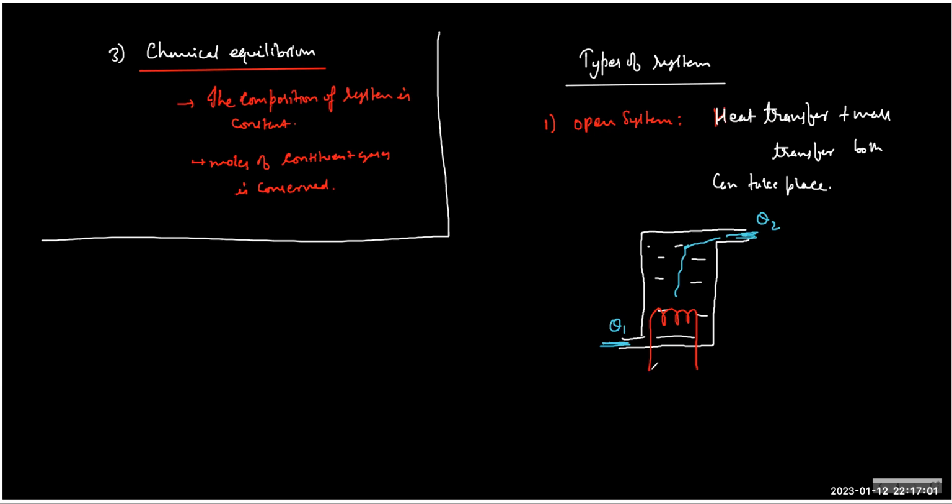So if I say dm is the mass entering the geyser and dm mass is coming out of the geyser, then how much energy has it gained while going from the inlet to the outlet? How much energy have you received? The energy received is mass times specific heat of water times (θ2 minus θ1). A heater will have a specific power to deliver the heating. So dQ by dt is how much? dm by dt is called the mass flow rate.